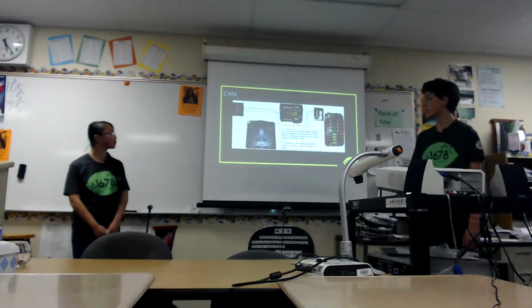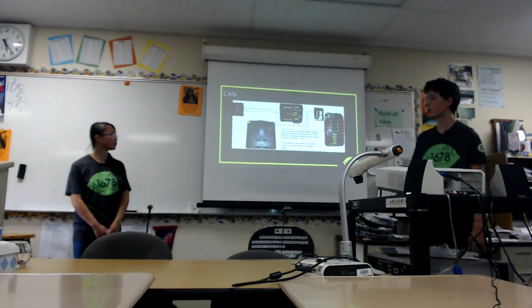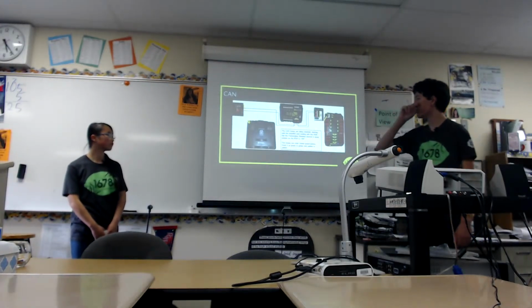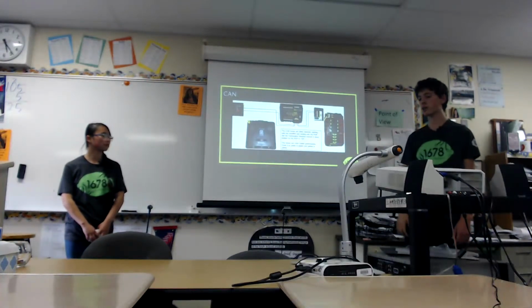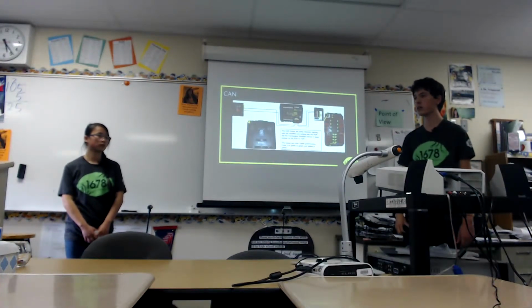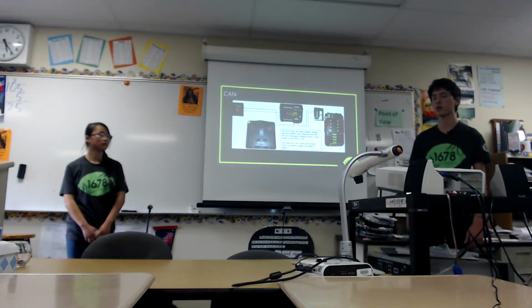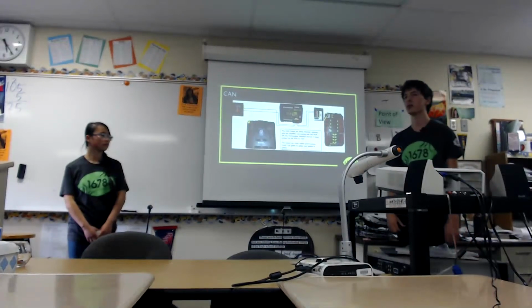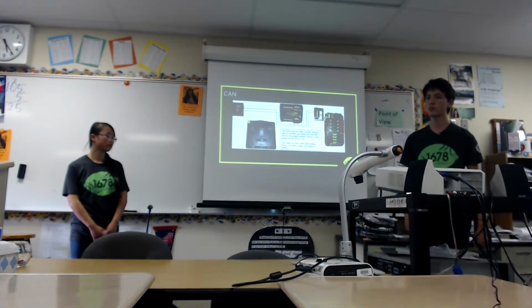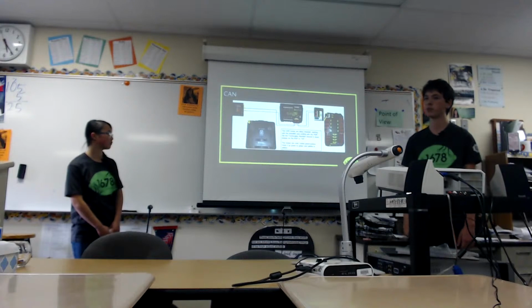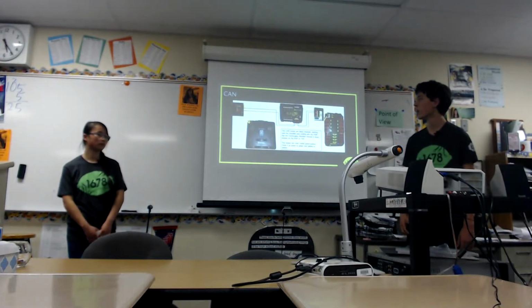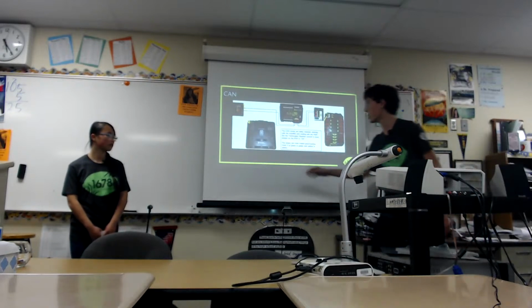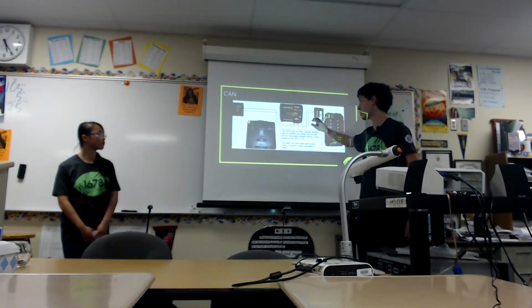And so the 3 main CAN components that you need on your robot are the RoboRIO, the PCM, and the PDP. And with the PDP, you've got the terminating resistor, which is technically the 4th but not really spoken about, an important part of the CAN loop. The terminating resistor is required to reduce signal reflection back through the CAN loop, which can mess with the signal. And when you're daisy chaining all of the CAN components, the nodes can just go anywhere along this circuit.